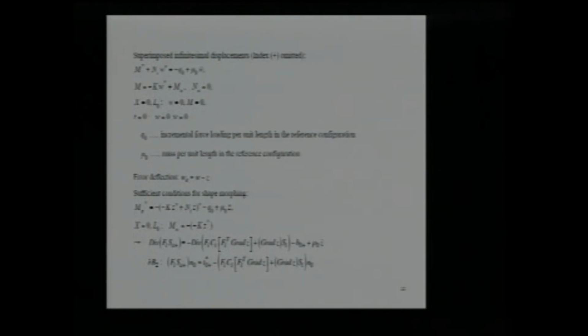This is the actuation stress, again, a quasi-static equilibrium condition for the actuation moment here, second derivative, two primes, as usual in structural mechanics. And one has to distribute this actuating moment in order to solve this equation. Now, in order to check if this works, it is necessary to formulate this Neumann type integral appropriate for the beam.